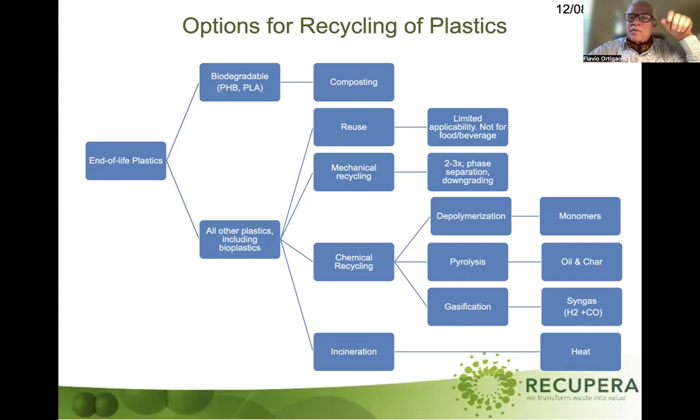And of course, you have the oil and the char. The char is carbon, but carbon contaminated with everything that was in the plastics. So it's not really pure char. But there are applications for those chars. If you go for specific chemical applications of the pyrolysis oil, not burning it, it can be interesting. But the technology that I chose to drive is gasification.